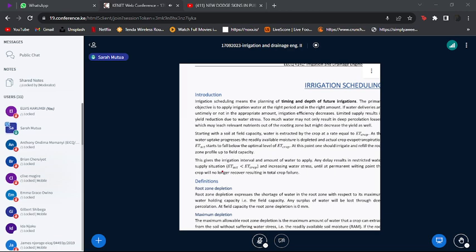When water comes from a river and is transported through an earthen canal all the way into your irrigation scheme, you can have evaporation losses, and deep percolation or infiltration losses, and so you also have to add that water in the amount of water that you are supplying, or have to store for that particular irrigation.